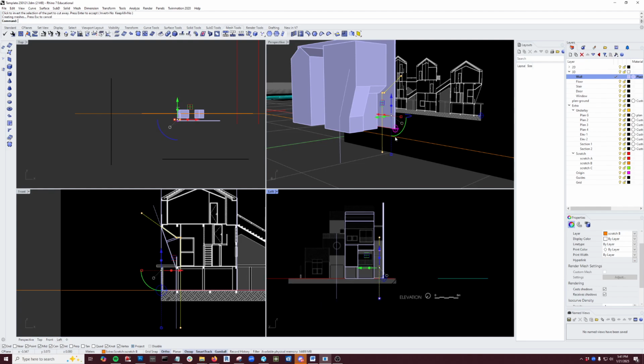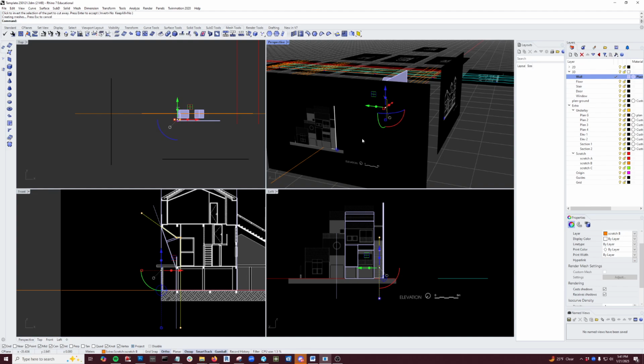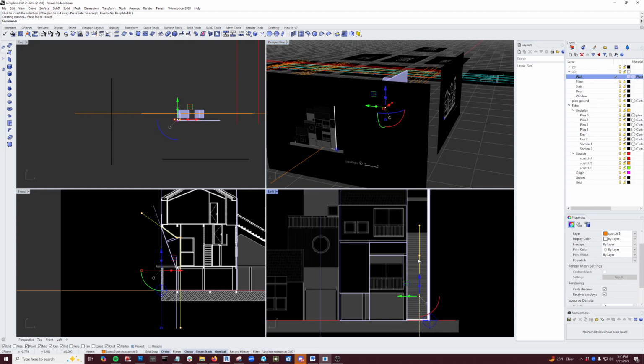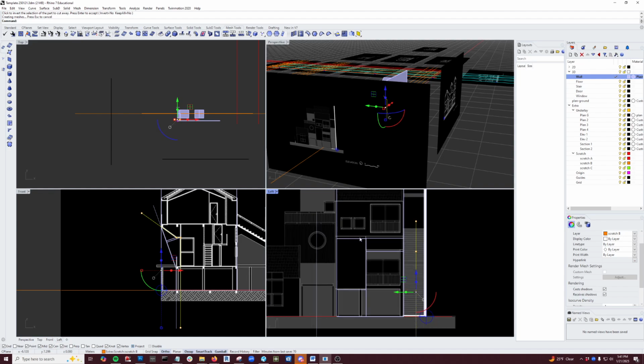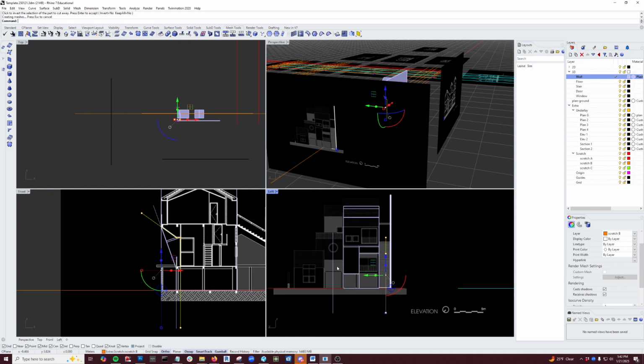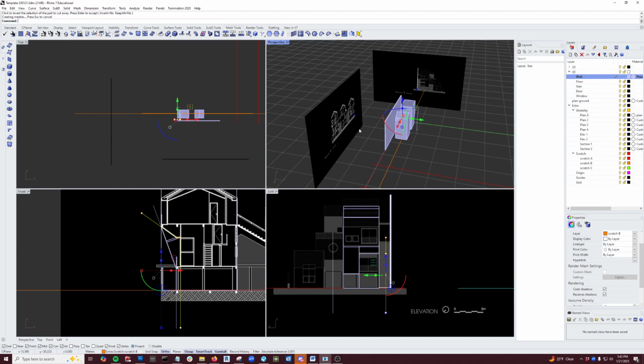And what's kind of cool is when you look, I also set up this elevation. And when we look in X-ray in the left view, you can see that it's already starting to line up with the elevation, the way it's drawn. So this is a really great way of working, I find, because it does a number of things. One is it allows you to really understand the form in a three-dimensional way, especially when it's got a complex section. And then two is it allows you to start to think about the drawings and the model as all being referenced to one another in a very, very precise way.